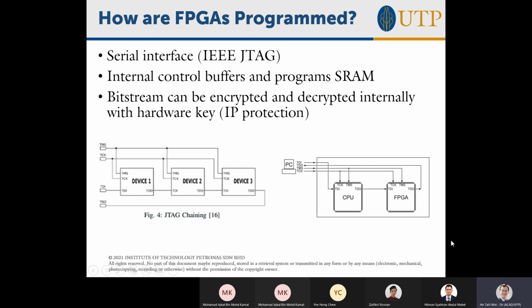And then that CPU is going to connect to a JTAG controller, and that JTAG controller is going to send a long serial string of bits into the FPGA, and the FPGA is going to actually push that serial string of bits into the SRAM. But it's got additional control logic. You will read it serially, then you'll buffer it, then when there's a parallel data word, it's going to update and write the SRAM in its own internal way. So do you understand how FPGAs are programmed?